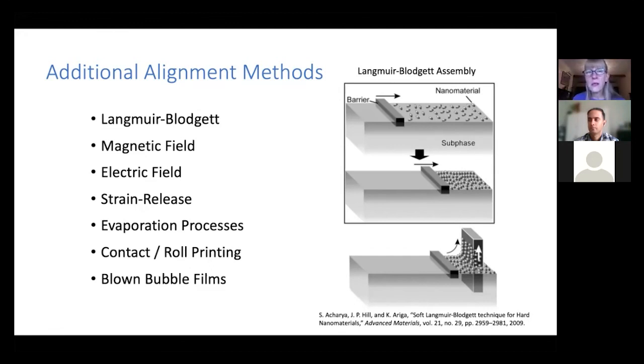Under steady state operation, it's a mass conserving process, right? The cross-sectional area times the incoming velocity is equal to the cross-sectional area times the outgoing fiber velocity, because you have practically no change in density. So you can easily control the outer diameter and therefore the gap dimension.